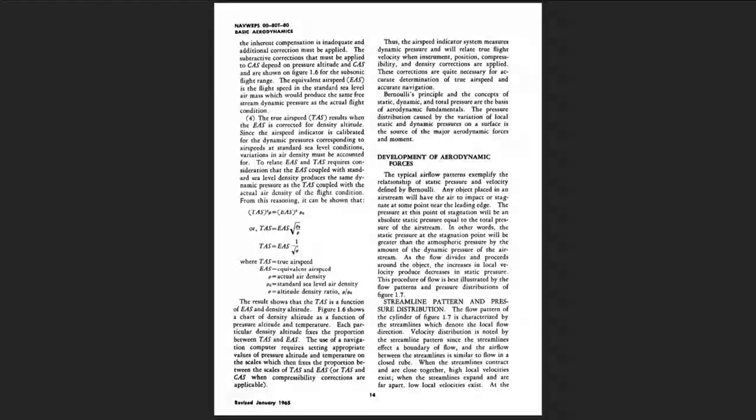Bernoulli's principle and the concepts of static, dynamic, and total pressure are the basis of aerodynamic fundamentals. The pressure distribution caused by the variation of local static and dynamic pressures on a surface is the source of the major aerodynamic forces and moment.